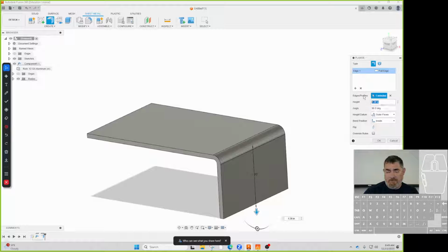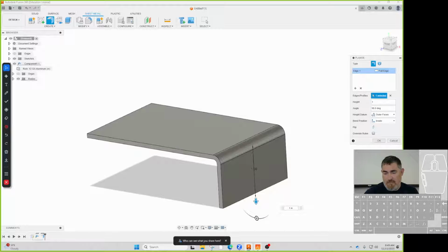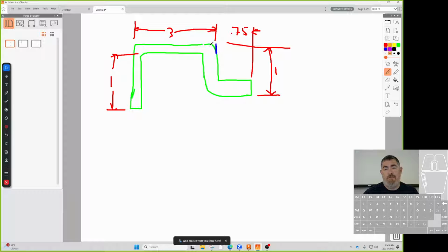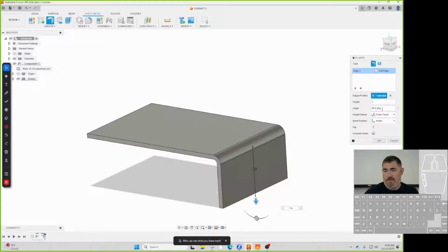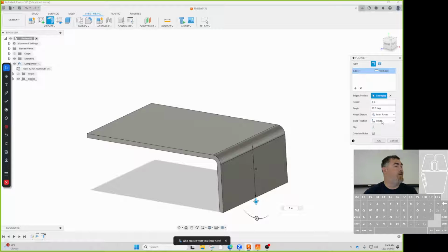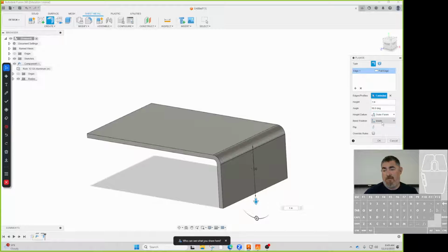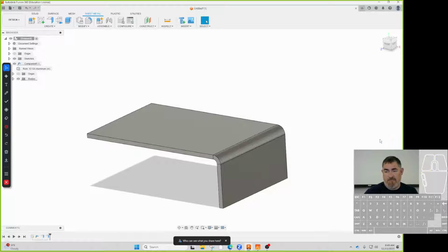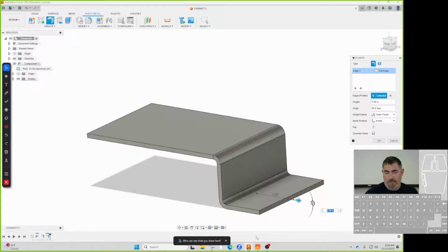And then my height, it's going to be 1. Is the height from the outside or the inside? It's from the outside, right? It's the shorter dimension, because here it'd be longer. So it's the outside there. So I'm going to tell it outer face, because if I do inner face, you get longer. So no, I want the shorter one, go there, say okay. Now I can do it from here going out this way.